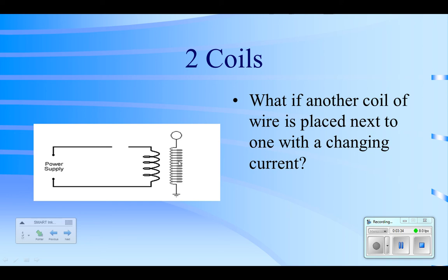And so we can actually get something that seems kind of strange, that as we close this switch, we'll suddenly get current in this coil for a brief moment. Now, only because while the field is changing, while the current is changing, this field gets bigger and crosses over the coils here, and while the coils are being cut, then voltage is being induced. Once the field reaches a steady state, then this all stops.